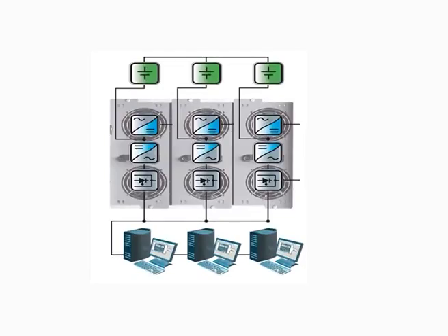It first converts the AC voltage into a battery compatible low voltage DC using circuitry called a rectifier. The rectifier supplies power to the inverter, the next stage, in addition to charging the batteries. This direct current is then converted by an inverter back into highly controlled and regulated AC.